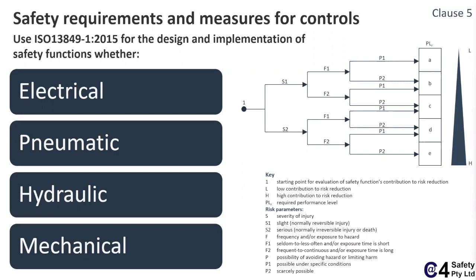And each of these performance levels, as we all know, relates to a probability of dangerous failure per hour. That really does force the practitioner to use quality components. Quality and mean time to dangerous failure aren't necessarily the same, but usually so. So up here you might have the Dick Smith micro switch, and down here you've got the top quality. What would you say? No, we won't mention any brands. But down here you've got the very high mean time to dangerous failure components, essentially taking you into that performance level E area, giving a performance level E.